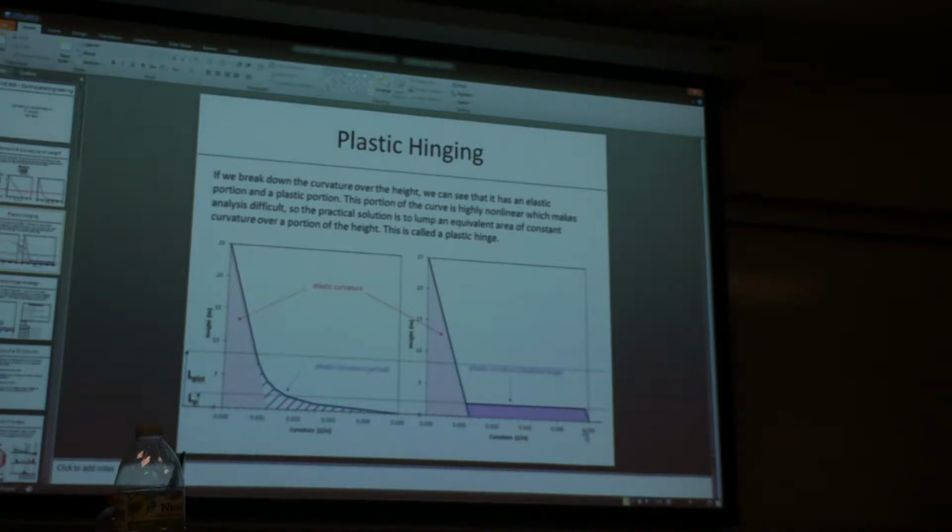Right? But you're not necessarily interested in this force, because how this behaves with respect to curvature isn't necessarily dependent on this particular system with this force right here. It's kind of generic. So you're saying, well, for a given level of curvature at this cross-section, I'm going to get this response. And so you can then take that generic point of view and put that in specific structural analysis models. And that's where we'll be going after this.